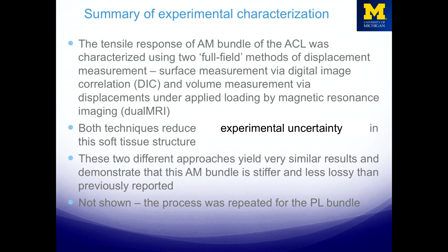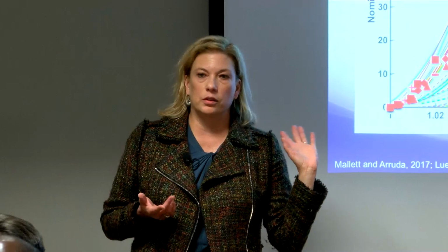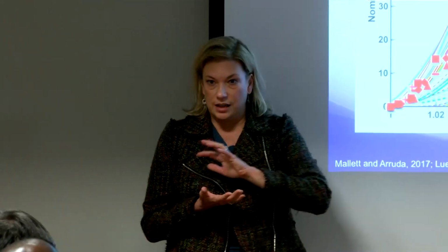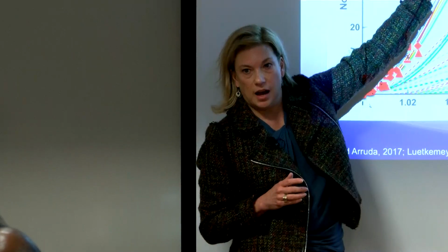Yeah? Go back 2 slides. When you look at the higher stress ranges, are you able to? So we weren't able to with our first setup. Good question. With the MRI setup, we were only able to go to 150 newtons or something of force. So we've redesigned. We've got a stiffer load frame, a higher capacity load cell, and we're in the process of refining everything we've done to get even more accuracy and get up to higher loads.